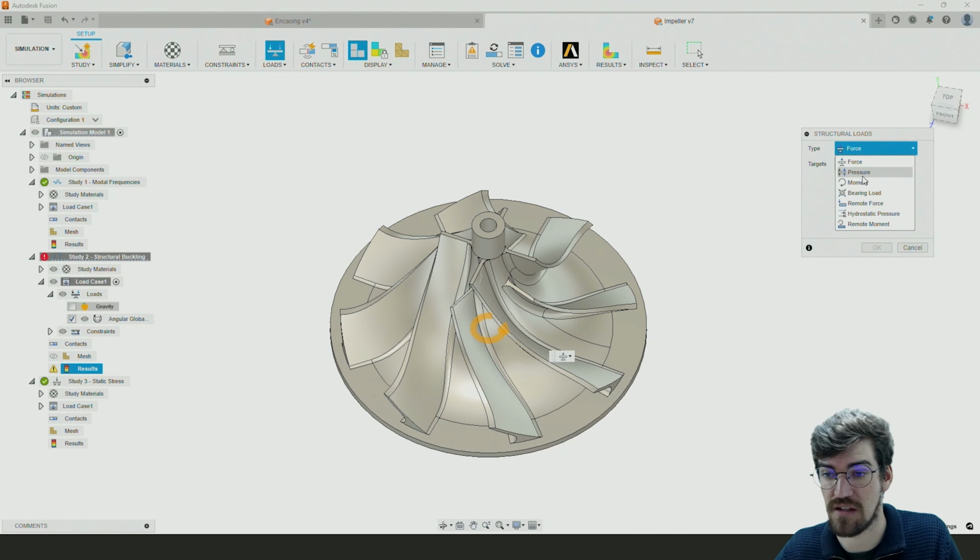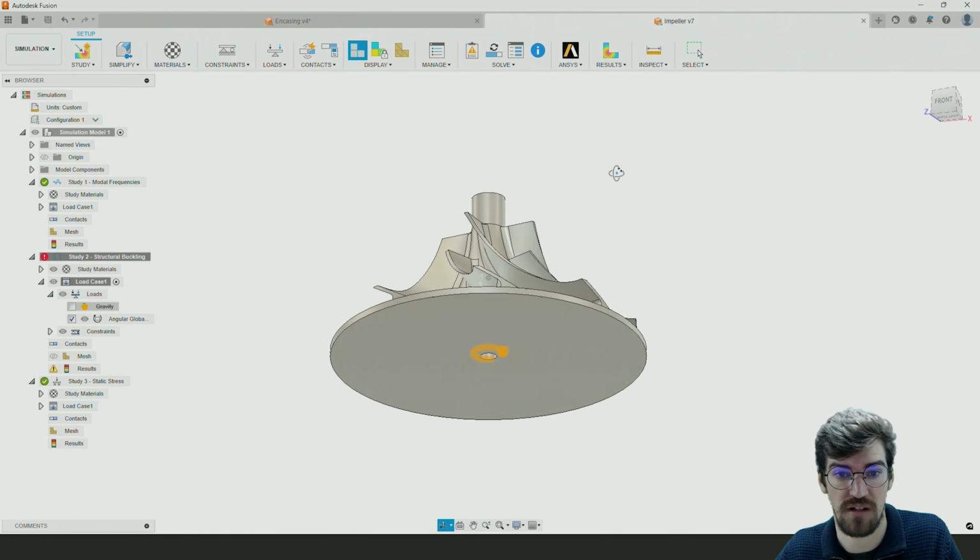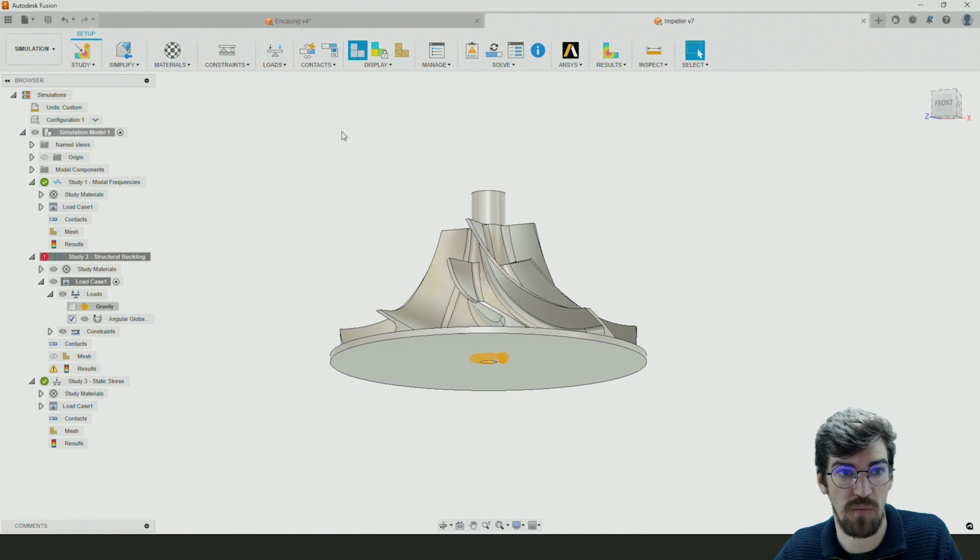So we can come in and either apply a bearing load against it or a moment against it as well. Maybe a remote moment or so on. I'm just trying to have a quick look. Potentially a bearing load on this one, although what we do potentially want to have a look at might be a case of actually just locking down the pin constraint a bit more.